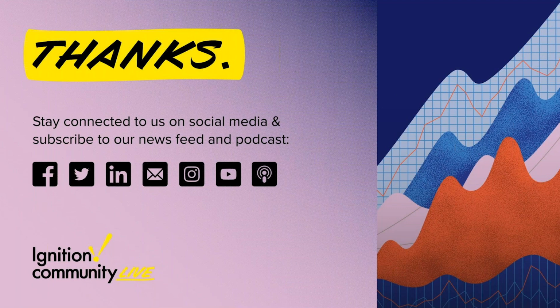There is a couple of questions here that I would like to touch on that I think are worthy of a mention. Does Opto 22 perform closed loop control based on a feedback signal? Yes, there are 4 PID loops built into the Rio. So you can configure those 4 PID loops to look at an analog input and control an analog output for sure. Benson, I'll let you talk to this one.